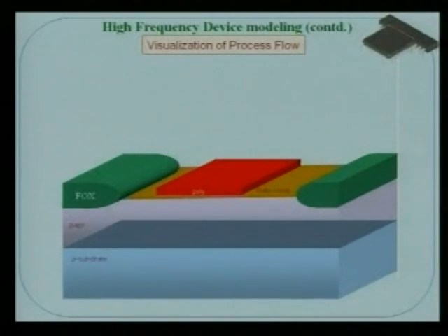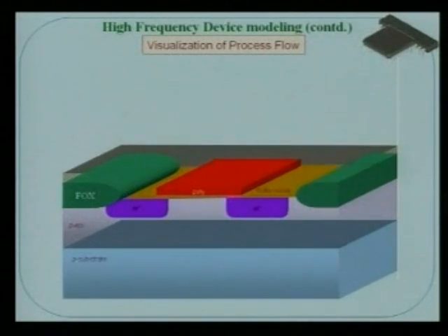On the top you have the polysilicon. Polysilicon is almost like a metal. It is polycrystalline silicon, and conductivity is pretty high. It is not metal, but polysilicon is used because it's the same silicon process, grown by either sputtering or CVD. Then you form the source, the gate and the drain, and this is your gate layer. You have the N plus, because this is the P layer. On that you have to grow the N channel, so you have the N plus source and N plus drain. Then you have the vias or contacts for the source and the drain.